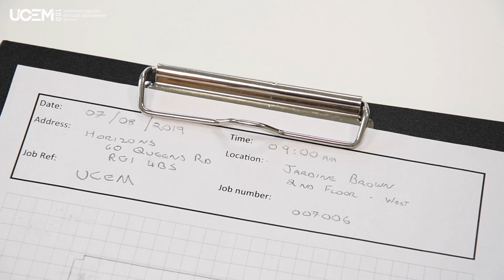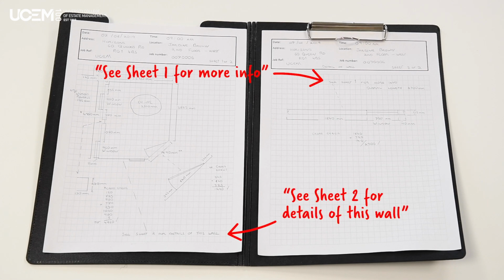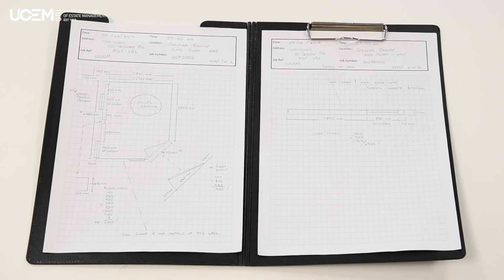Remember to record the date, time, and location of the drawing, plus any other details required, for example, a job reference or number. Don't let the survey notes get too cramped. If parts of the rooms contain complicated details or fittings, record these on a separate drawing or a sheet of paper, and take a picture for later clarification.